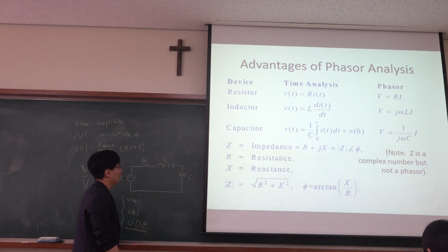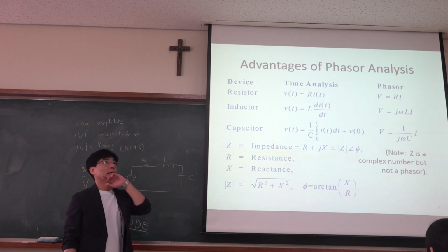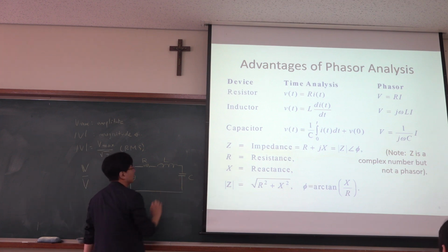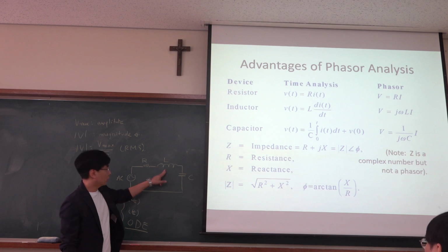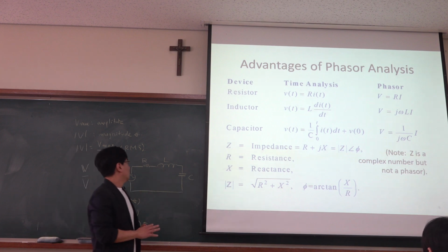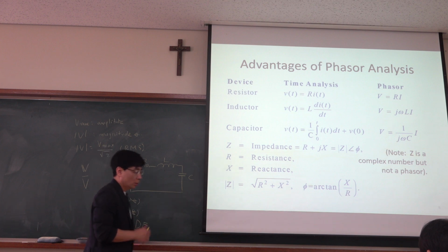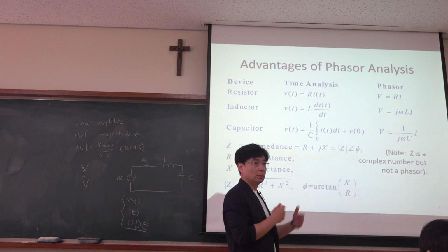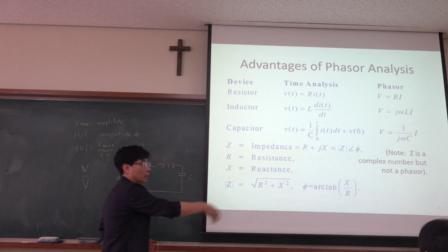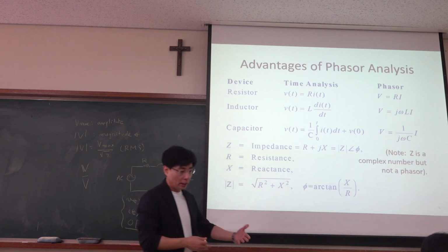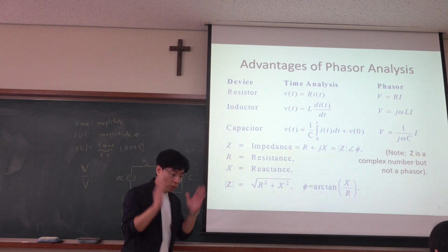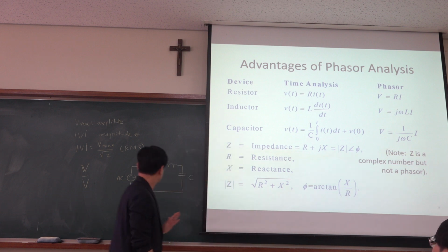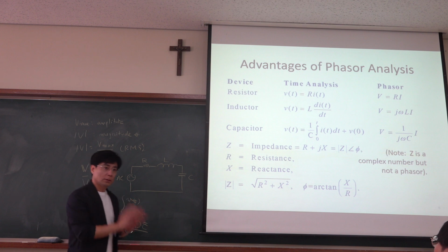At time 0, what was the initial amount of charge in this capacitor, or the initial current in this coil, etc. But as time goes on, we quickly go through this transient period and go to a stationary region. After that, we can apply phasors. If you only focus on the stationary behavior, you don't need to solve this ordinary differential equation. Just focus on phasors only.